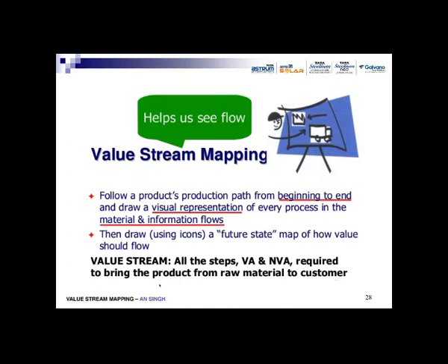So now those metrics that we have explained have to be used while value stream mapping is being done. So what is value stream mapping? It is to follow a product's production path right from beginning to end and draw a visual representation of every process in the material and information flow. Then draw a future state map of how the value stream makes the material and information flow.